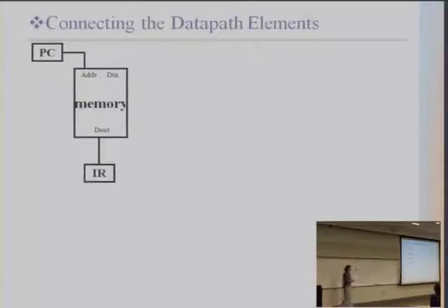So why do we need the instruction register? Can we just, every time we need it, basically read the memory? Theoretically, we could, but it's not very efficient. So we take one extra register called the instruction register, store all this information, and then we will see. First, we have to fetch the instruction. Then we need to decode it to figure out what the instruction is. Then we need to fetch these registers to perform the operation. So we want to have the whole thing in one place where we can access it easily.